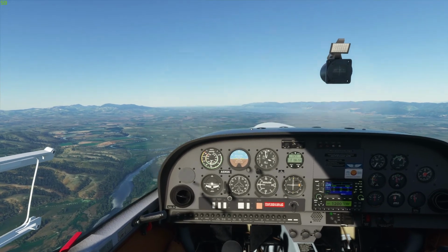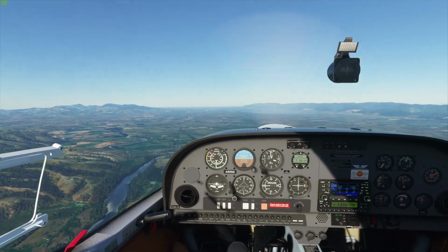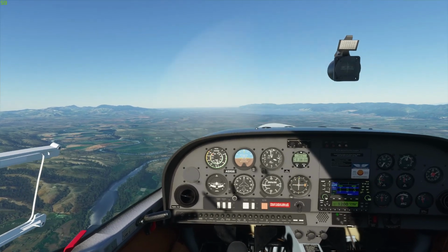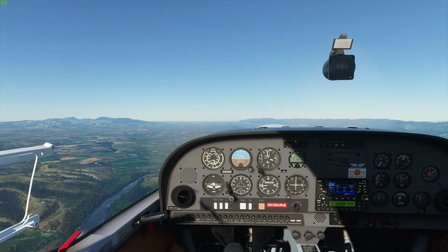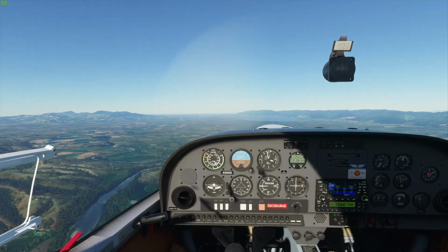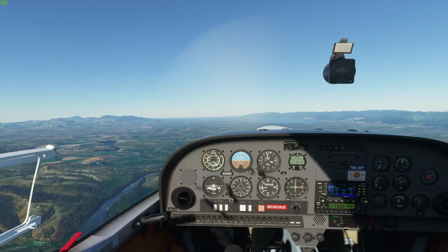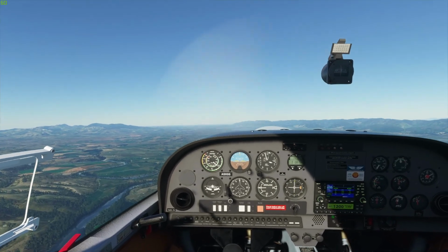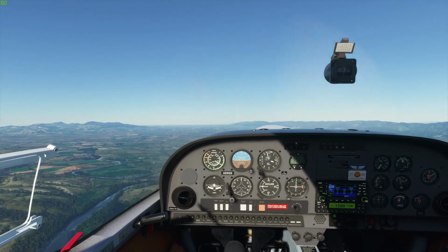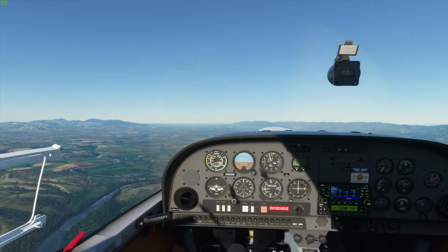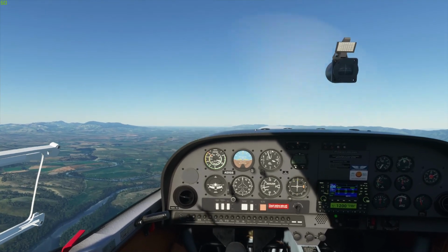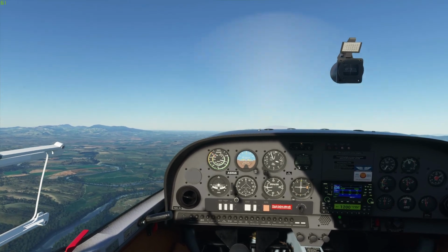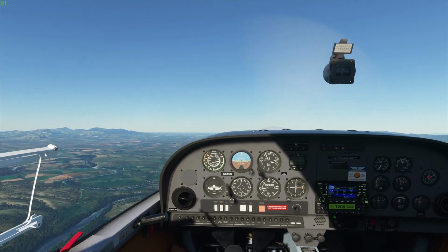So I've just closed the throttle back to full idle there. And now I'm just increasing the elevator back pressure to maintain 3,000 feet. We can see the speed is decreasing. And I'm pretty much going to trim for about the speed here. So that means I'm increasing the elevator trim to about this point. And now I'm not going to trim anymore. And she's just sitting there. So once we got that first 20 knots off, 20 or 30 knots, it stayed pretty steady.